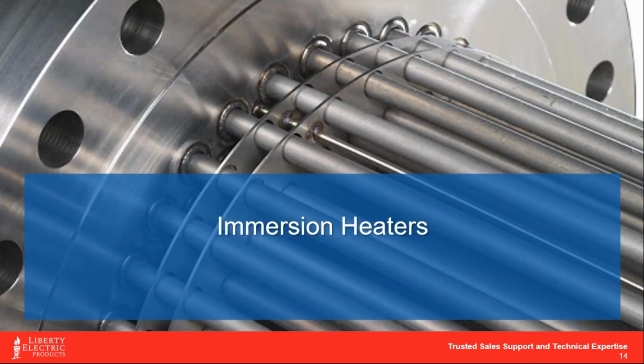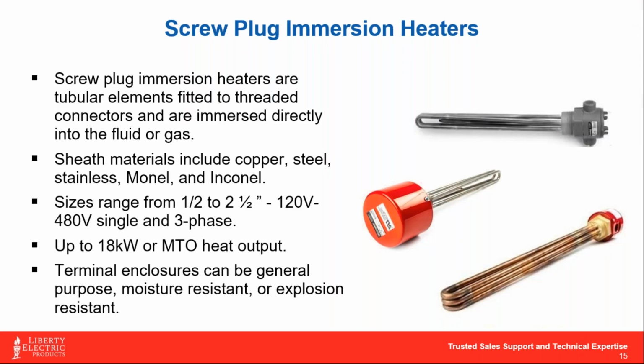Immersion heaters. Immersion heaters are really common, and probably the most noticeable one that we see a lot is screw plug immersion heaters. These are the smallest in your immersion heater family, and these are connected to whatever appliance or device they're going into with a threaded NPT connection. So they just literally screw right in, and you wire them up and away you go. A common application for these is something like an electric water heater.